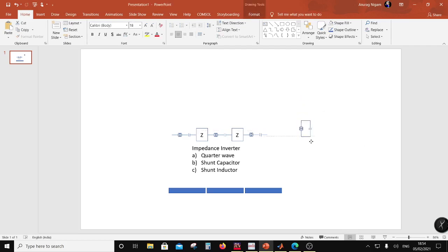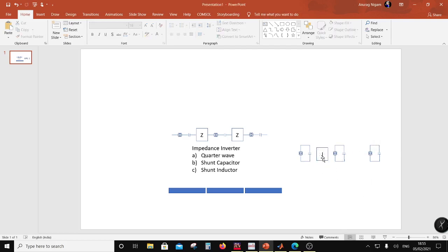Okay, so I can also represent the same bandpass filter using these resonators, and these resonators are separated by an admittance inverter. So this is a parallel version of it, right? So I can have J in between. Okay, so the idea is to design this filter using only one resonator and then using an impedance inverter in between, right?